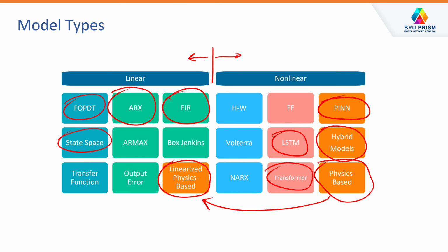Okay, so one of the add-ons to Gekko, this is a platform for system identification, and this is the Seek workbench. I'll just mention it a little bit. You can run this through Seek, or you can run this through a Jupyter notebook as well. But it helps you identify some of the models that are important for control applications or building soft sensors or inferentials. So if you come to this link right here, you'll see the Seek identification package. I'll give a little bit of a demonstration of that as well. You can also do pip install seek-sysid.